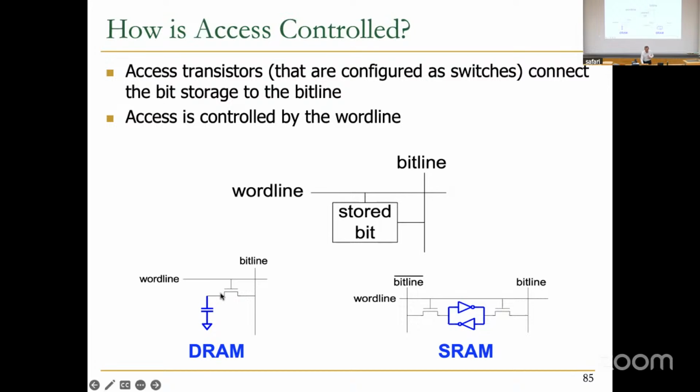And the key is you can make this capacitor extremely small. You can make the voltage level at the bit line relatively small, and you can sense very small changes in charge. That's the idea. So people build these DRAM chips today where you can sense very little changes in charge. That's how you can make things denser and denser and denser. But as you make things denser, the charge over here can get perturbed in some other ways, like noise. So that's why RowHammer, etc., happens also.